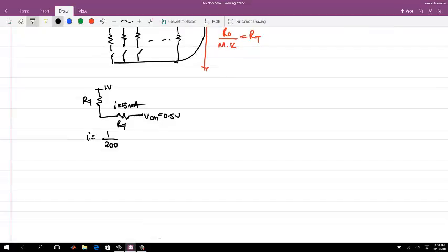This is the ideal one where you are transmitting the maximum swing, and now let's transmit half the swing. Still, let me just say this is VCM. You have R up and R down. What can you comment on the current through this resistor? Let's call it I signal. What is the I signal? Is it lesser, greater or equal to 2.5 milliamperes?